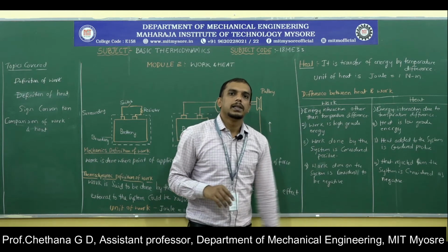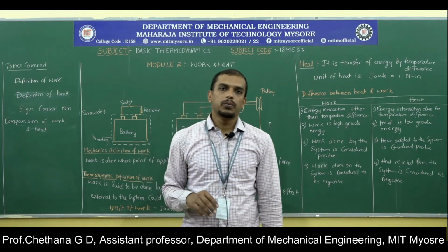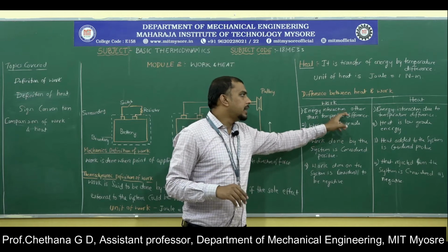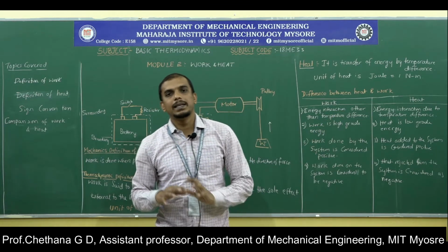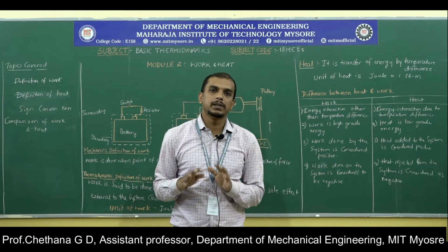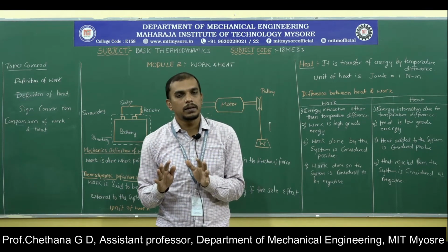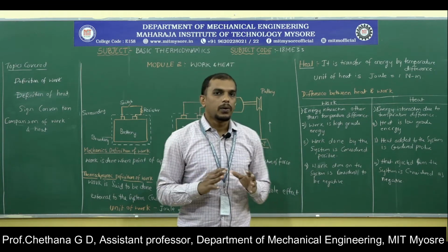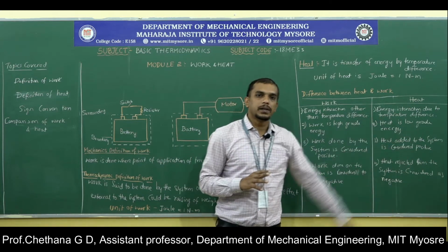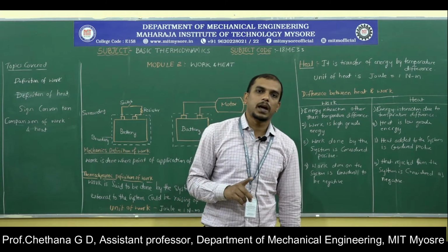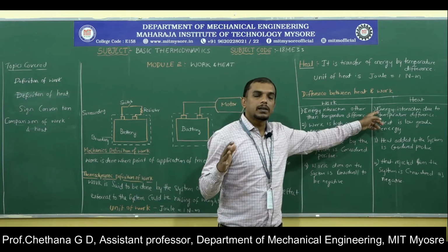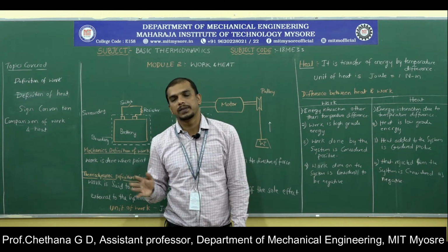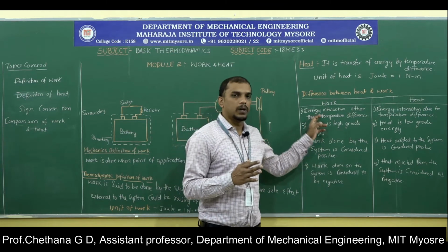Now we will look at the difference between heat and work. Work is energy interaction other than temperature difference. So all the energy interaction other than temperature difference, we are calling it as work in thermodynamics, whereas heat is the energy interaction only when there is temperature difference. So if the energy transfer is happening because of the temperature difference, that is heat. Now any energy transfer other than temperature difference, they are work.